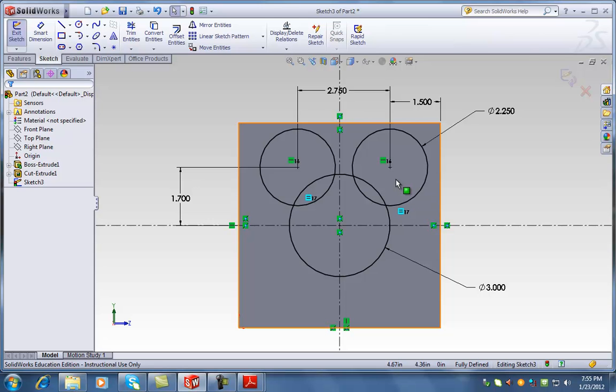The same thing is going to be asked by SolidWorks. It doesn't really know which one you're trying to extrude boss base. So what we have to do, we have to clean up the sketch in such a way that it's a continuous flow. So we cannot have overlap just like here.